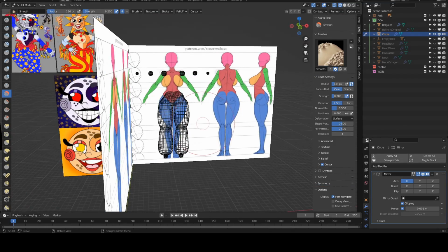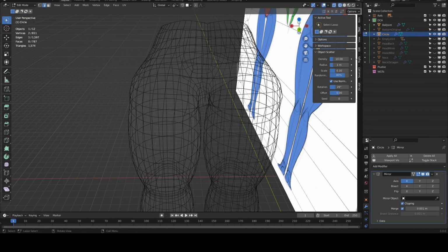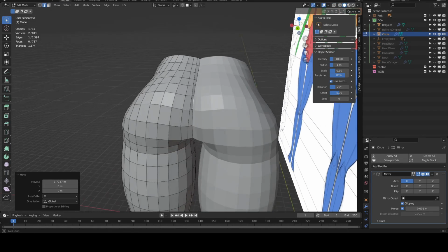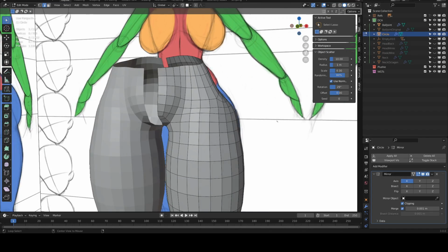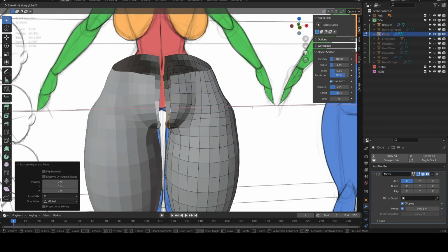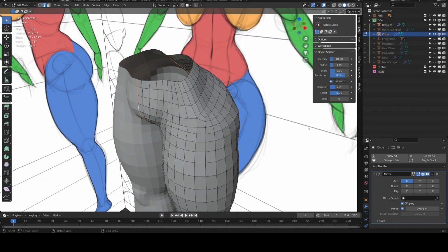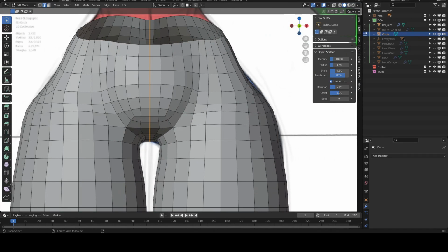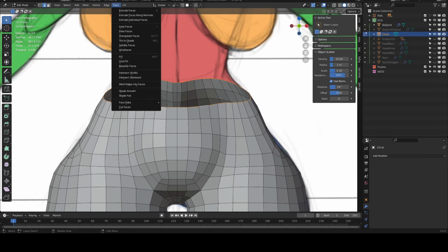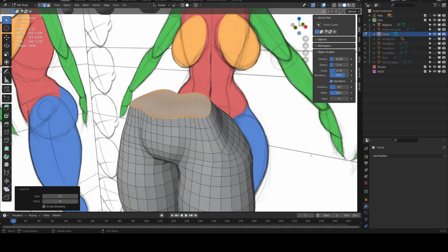All right. GX. Go ahead and delete these verts just so we can have it being smooth going across. There you go. Here, apply. Select all through here. 48. Face grid fill. Turn it to where it looks about right. There you go. Simple bending.